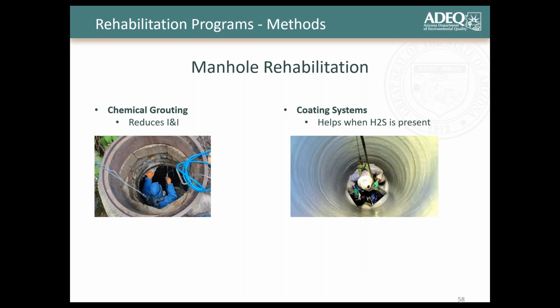There are different coating systems, right? We've used this a lot in areas that are heavy with H2S. You just coat the whole manhole structure. It really helps you maintain the integrity and structure of that manhole.